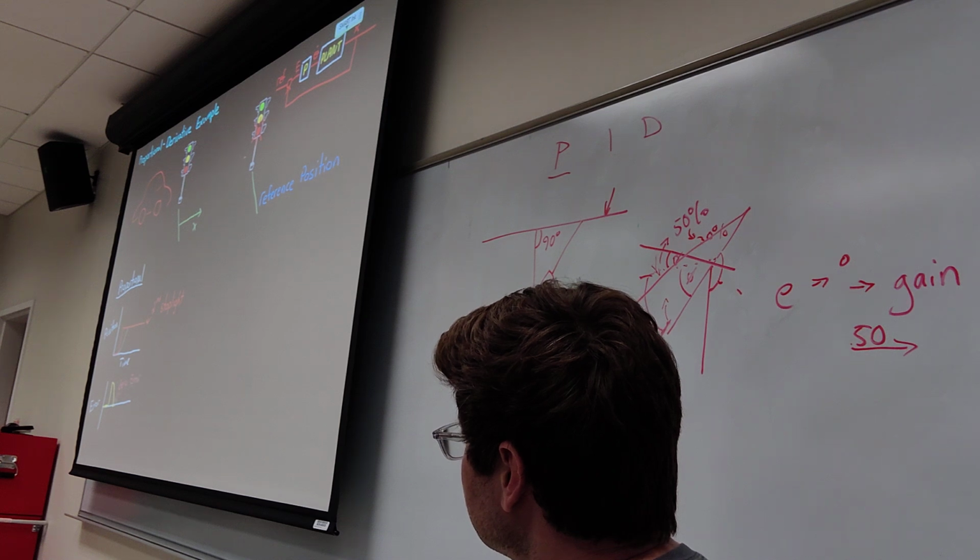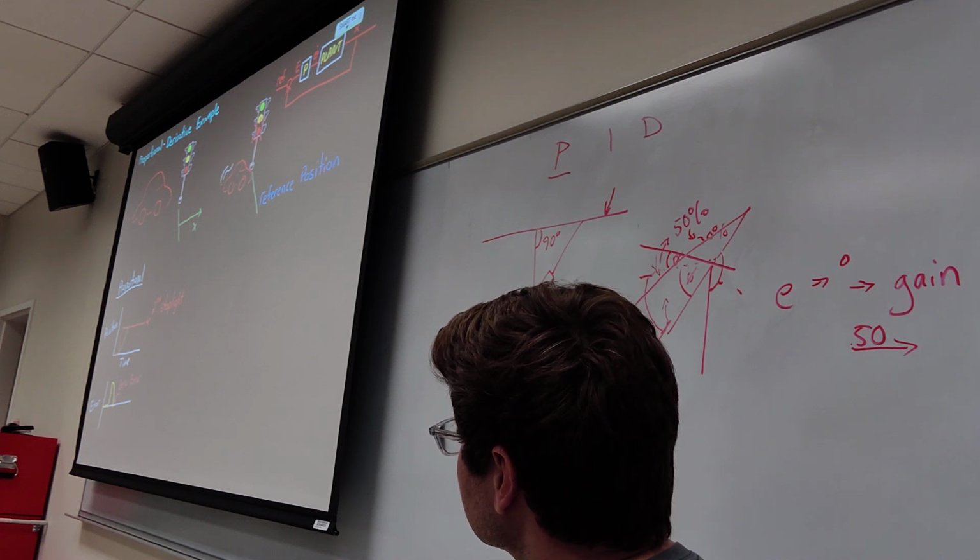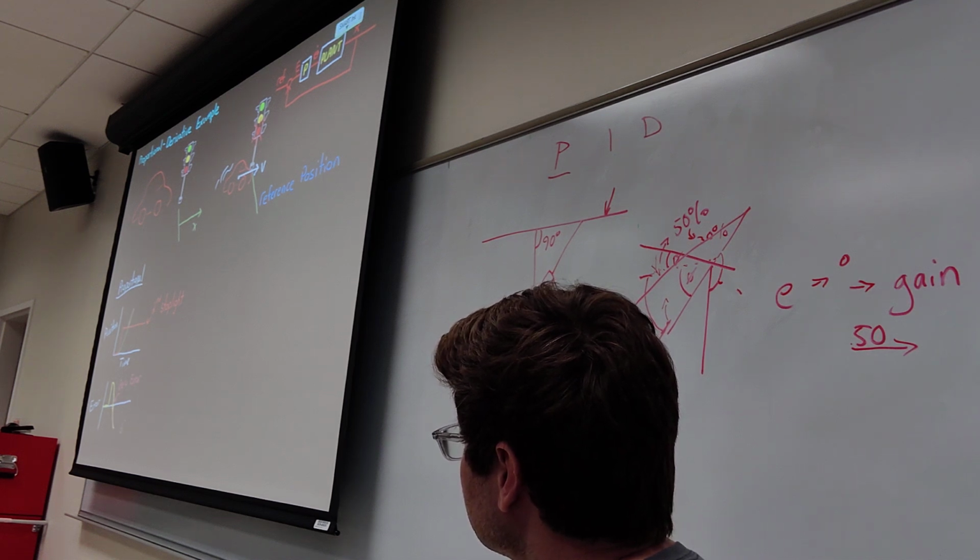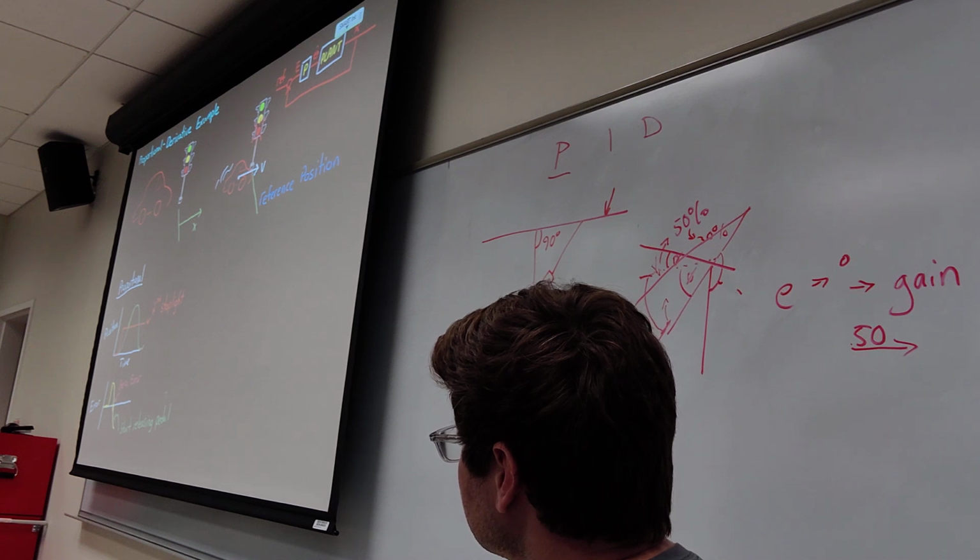So everything's okay, right? Wrong. Not only do you have all that acquired speed, but you're still pressing the pedal down, and you blow right past the light. Now, once you pass the light, the error begins to grow negatively, and you start releasing the pedal, and eventually you put the car in reverse and start heading back to the light. But you have the same problem in that direction, and you end up just oscillating back and forth.